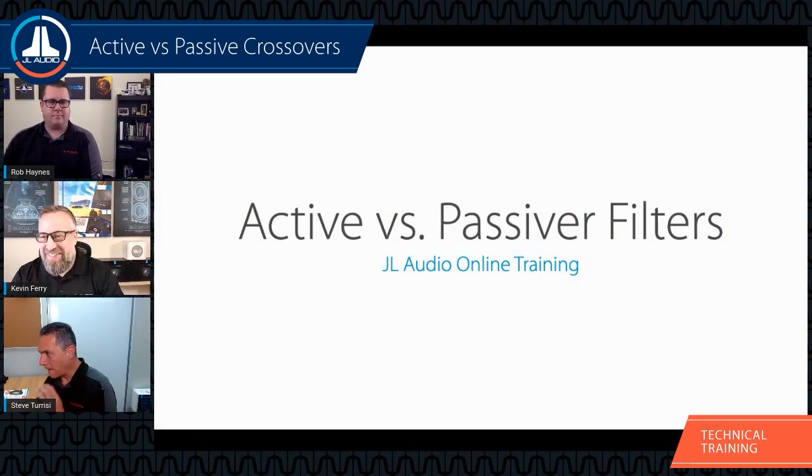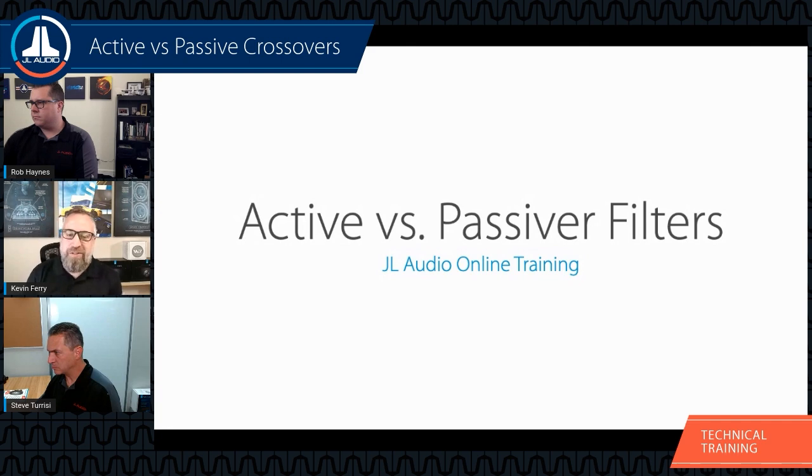I appreciate it, Steve. All righty, you got the right thing up there. Thanks, Rob. All right, so like Steve said, today's conversation really is kind of a conversation and discussion. We're going to go through a bunch of different stuff on active and passive filters. And why are filters so important? Well, no single speaker or driver can really cover the full spectrum of the audio signal properly. If we want to reproduce it all, we need to use different drivers and have them work together to cover that entire range. The proper use of high-pass, low-pass filters can give us excellent results when they are done properly.